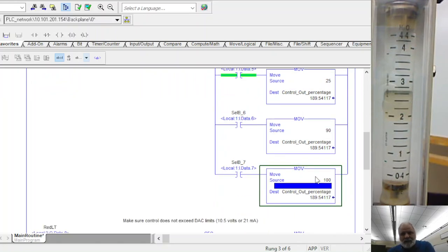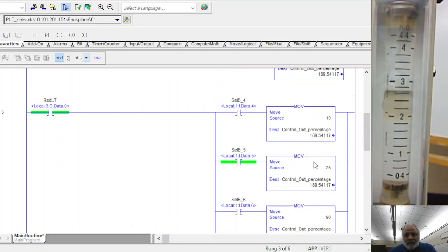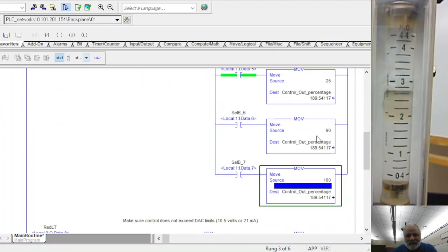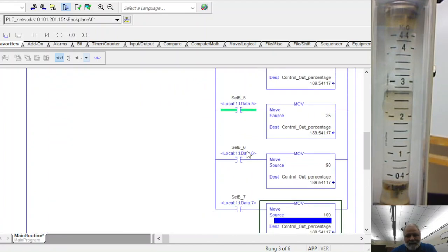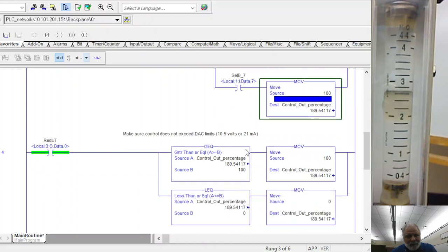And so what we're going to want to do is activate the output control valve, and we want to start it activating when we flip the switch, so it should activate at one of those if the system's enabled. Then we're going to limit our actual output so that the valve never goes below 0 or above 100%.